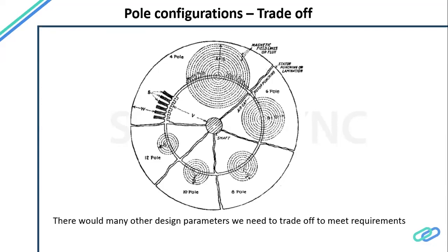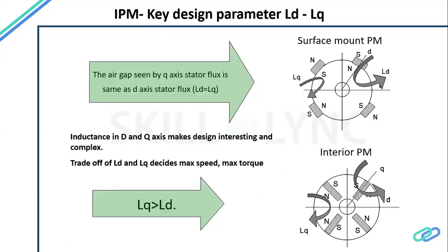because they fall in a sweet spot, or a golden mean area, where the switching frequencies and the size of the machine work out. You see the size of the machine, or the OD of the machine, shrinks as I increase the poles. This is a flux return path where you don't need so much steel on the outer, because the conduction is only in a smaller portion of it. So these are all the trade-offs, or design choices, that we have to ultimately make.